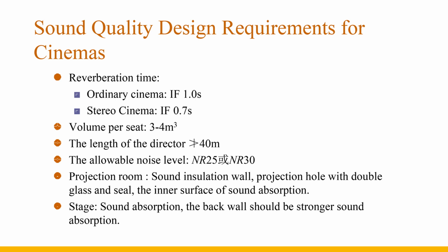However, because the sound level of the front row and the rear row will differ too much in a too-quiet hall, it is necessary to maintain a certain reverberation time to facilitate the uniformity of the sound field of the hall. The intermediate frequency is about 1 second.